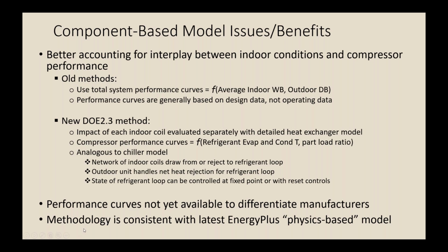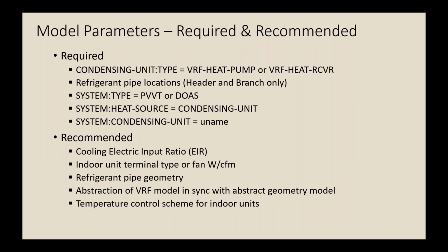One other thing to point out is that this methodology of a component-based model is consistent with the latest EnergyPlus physics-based VRF model, as they call it. And we actually studied that model quite a bit as we were developing because we wanted to have our performance curves be compatible with EnergyPlus. So people who use both programs or people who are developing for one program can use the same curves for the other. So I've tested that, and I'll show you in a little while the comparison between the curves of the two programs.